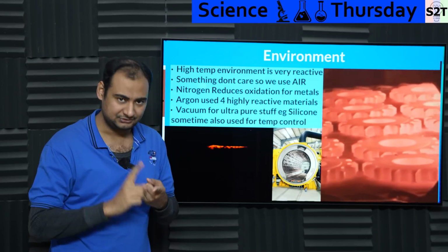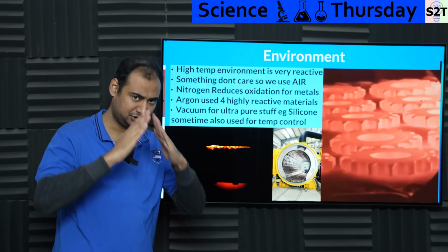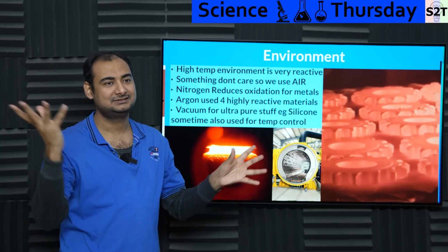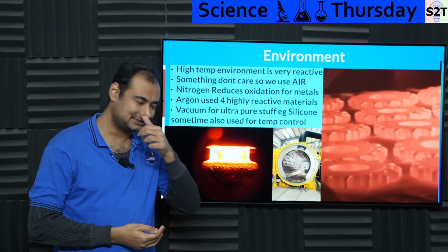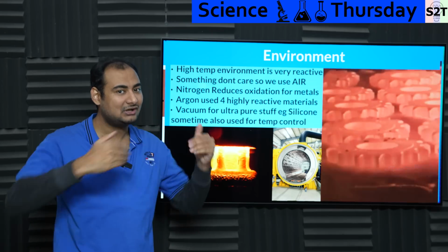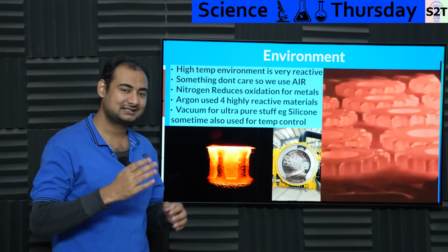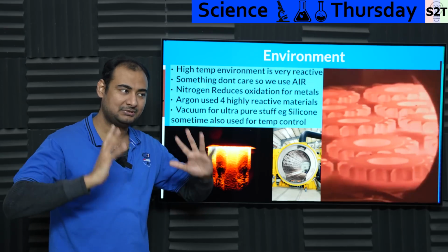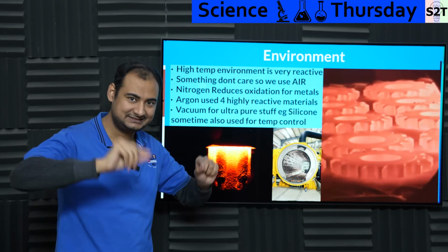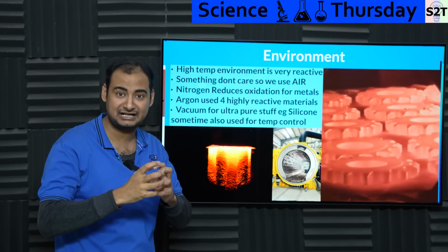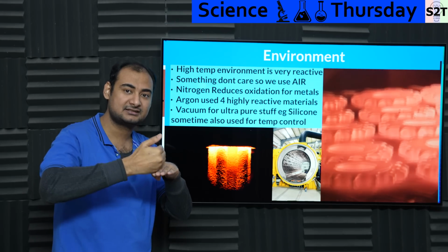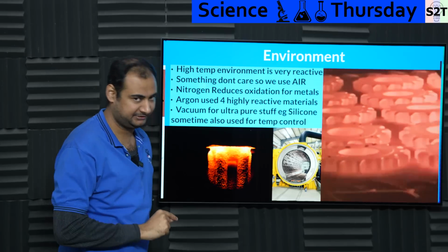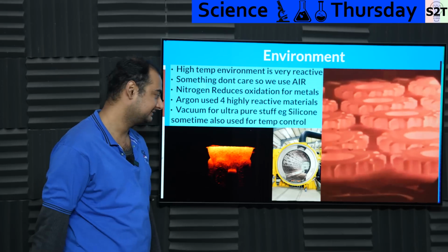Now, why? Well, you need a very high hardness in order to maintain the edge, the sharpness. Cool, awesome. But if you made the whole blade hard, the moment you strike two hard metals, kaput, it will shatter like glass. So hardness is used to handle the edge, softness is utilized to handle the shocks. That's how you get the two metallic system. The same thing is done in almost all modern metallurgy systems, where it's like, okay, which place requires the hardness? For example, gear teeth: you want the teeth themselves to be hard, but the core, so it does not shear or shatter, to be soft, but the wear surfaces to be as hard as possible. So all of these things require control of the environment, not just a black and white thing, control of that environment.